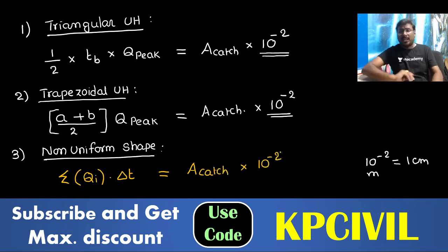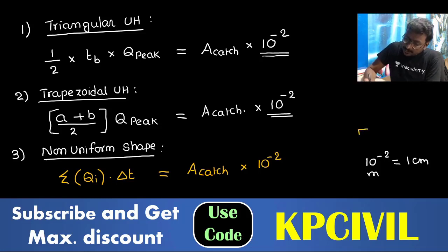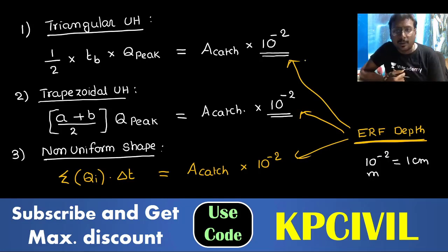So, in your exam, what will they ask? They will ask either peak discharge of direct runoff, peak discharge of unit hydrograph, or area of catchment. They don't give you runoff depth. Why don't they provide you runoff depth? How can you solve if runoff depth is not provided? In the data, they will not provide runoff depth or effective rainfall depth because that runoff or effective rainfall depth is equal to 1 centimeter, 10 power minus 2. That is what we have taken every time, 1 centimeter or 10 power minus 2.